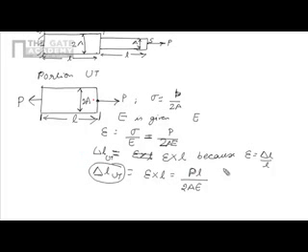Now this change in length is actually the displacement of this point T, because this portion is fixed, it cannot move, hence all the deflection will be occurring at T. So the point T moves like this by this much amount. So let's say if I draw it figuratively here, this is delta L of UT.